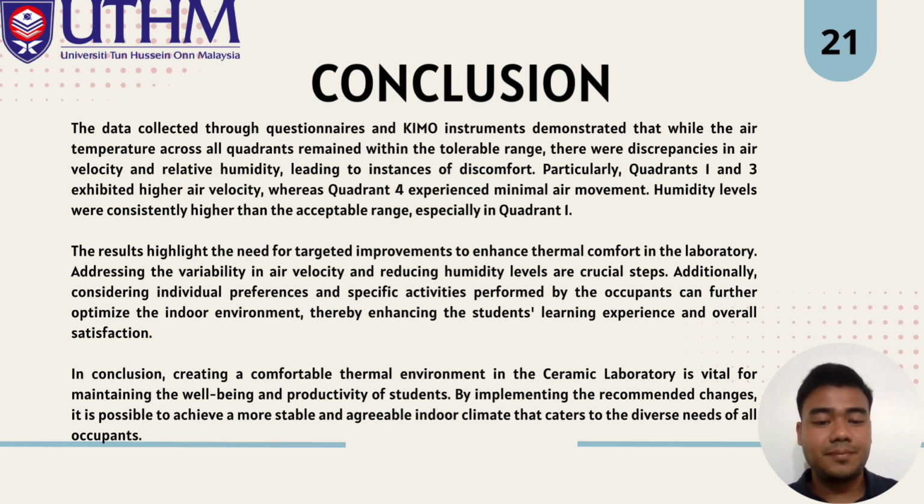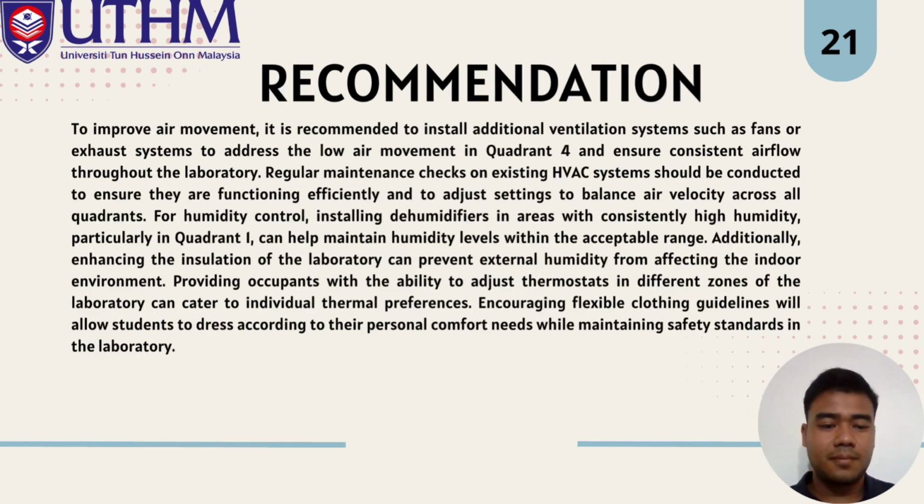For the recommendations, to improve the air movement, it is recommended to install additional ventilation systems such as fans or exhaust systems to address the low air movement in quadrant 4 and to ensure consistent airflow throughout the laboratory. Regular maintenance checks on existing HVAC systems should be conducted to ensure they are functioning efficiently and to adjust settings to balance air velocity across all the quadrants.